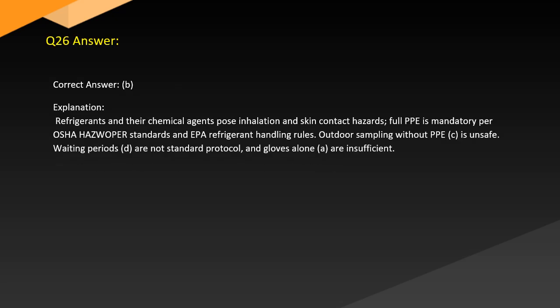Answer. Correct answer, B. Explanation. Refrigerants and their chemical agents pose inhalation and skin contact hazards. Full PPE is mandatory per OSHA HAZWOPER standards and EPA refrigerant handling rules. Outdoor sampling without PPE, C, is unsafe. Waiting periods, D, are not standard protocol, and gloves alone are insufficient.